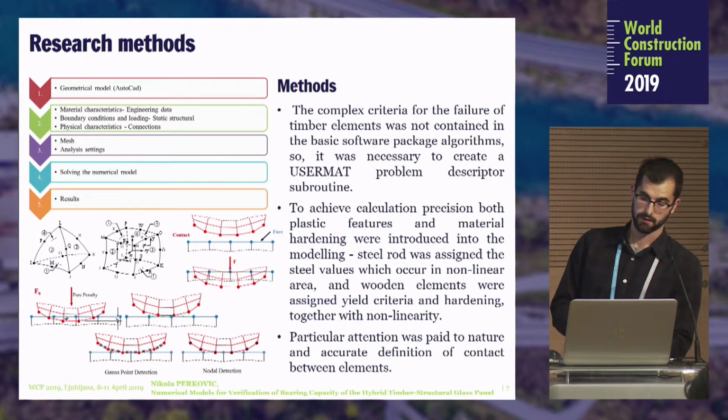The basics of ANSYS weren't enough, so to achieve the calculation precision, plastic features and material hardening were introduced into the modeling. For the steel rods, the steel values occur in the non-linear area. As I said before, particular attention was paid to the accurate definition of contacts.